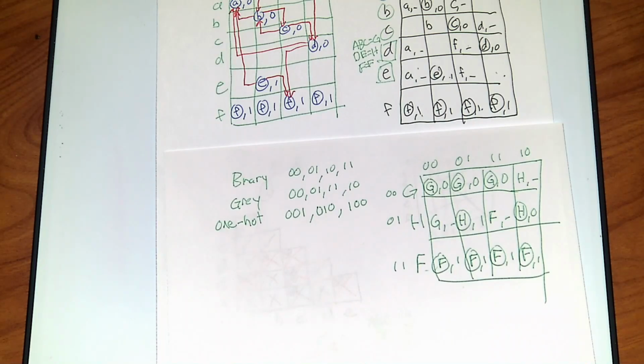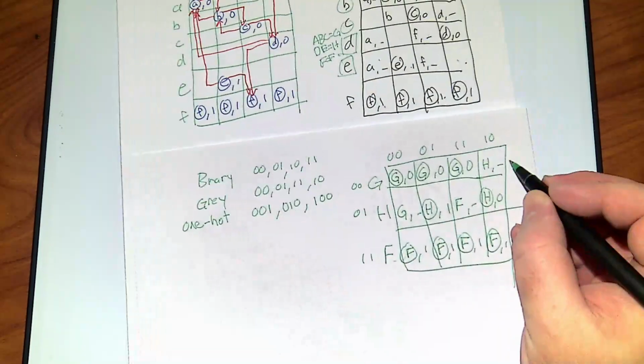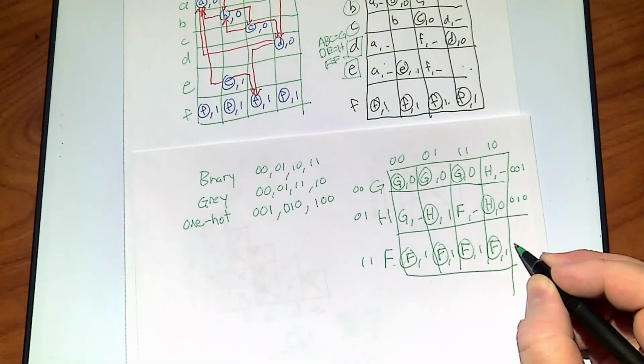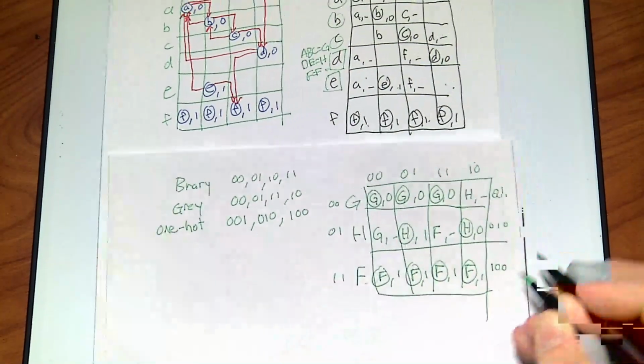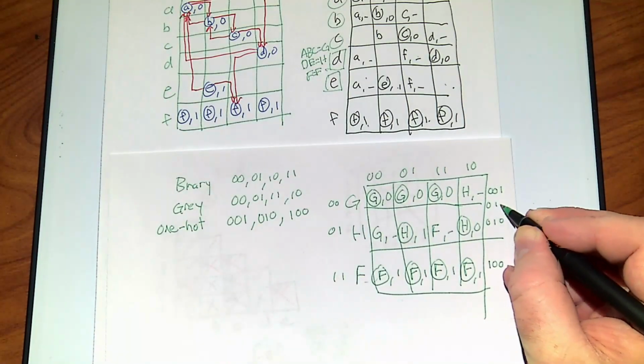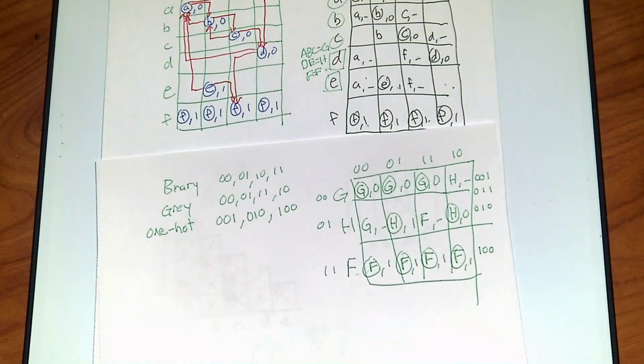So what we do is we generally make a transition requirement if I did one hot, where I just say, hey, look, this was my 0, 0, 1, this is 0, 1, 0, this is 1, 0, 0. When I want to switch here, I just say automatically when you're going here, I'm going to turn on the extra bit and then turn off the push. That's trivial, I just slow it down. I force an intermediate state. But it's so automatic that it doesn't really take a lot of thought, right?